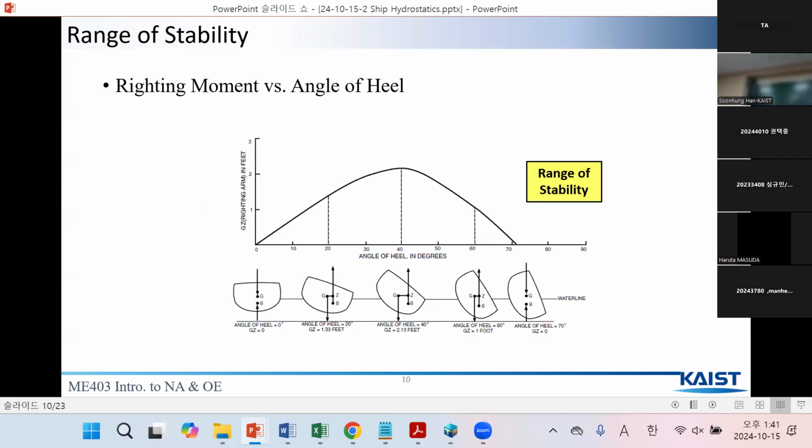So, as I told you, calculate GM for each angle of heel: 1, 2, 3, 4, 5, 6, 7, 8, 9, 10. I think it says GZ rather than GM, but it's the same, right? It increases as the ship is heeling, at some point it decreases and somehow it becomes minus. Right? Not sure. So before this is the range of stability. Also the area is important, the angle of heel and GZ. So this one you should calculate for the stability.